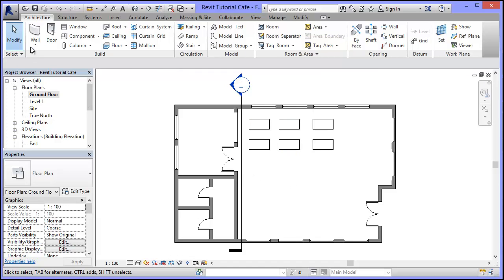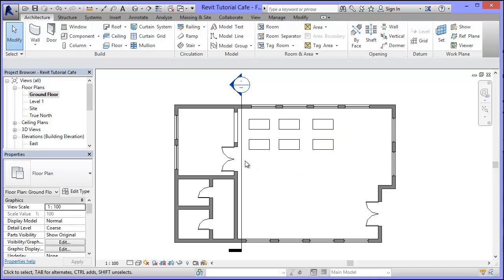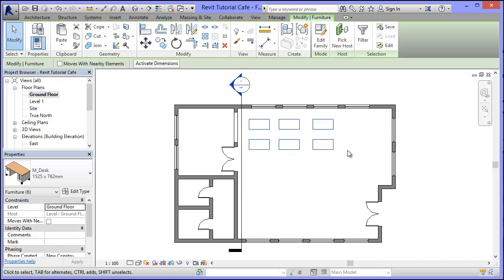So if I, in the modify panel selected here, drag my mouse over something, I'm going to drag it over this one here, and you can see at the moment nothing's happened. But once I've actually gone all the way over an item, it turns blue. It means it's selected, and that works with multiple selections as well. So if I actually grabbed all of these, nothing's happened to those 3, then they're selected, move up, then they're selected. So I've now selected all 6.